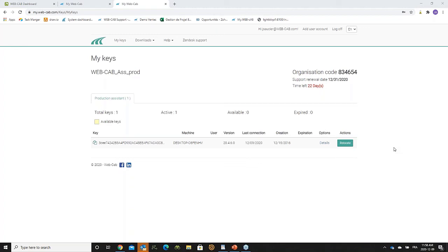The way it works, just so you understand, coming out from the CNC, the parts are already divided in three sections. One row for every part that needs doweling, another row for all the doors, and the other row for all the sides. So the edge bander received the carts like this, edge banded all the sides and gave them to the guy that works on the sides, the other one only on the doors, and the other one on the doweling machine. But the key is that they were able to increase their productivity to 150 cabinets per day in control. So working with the fixed rack like that, we were able to increase their productivity and get 150 cabinets per day in control, which is what they wanted.